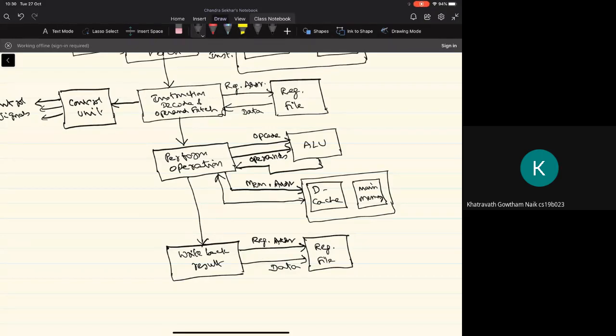And the time taken for floating point arithmetic operations is completely different from the time taken for integer arithmetic operations. So the amount of time taken for performing an operation by the ALU varies from one arithmetic instruction to another, and accordingly, the logic in the control unit has to wait for that period of time for the result to come from the arithmetic and logic unit.